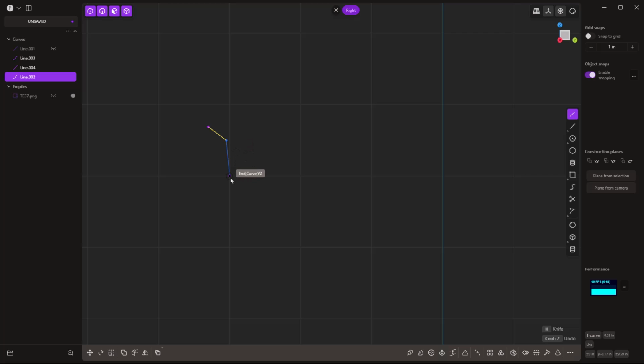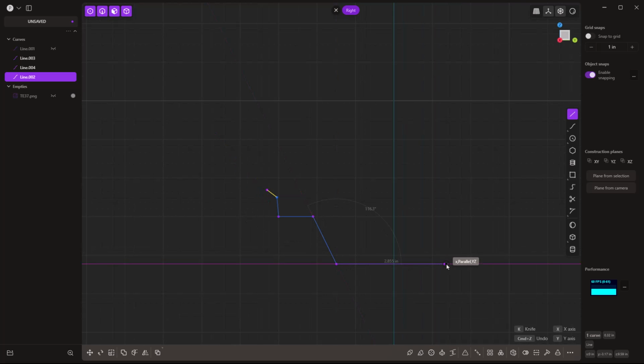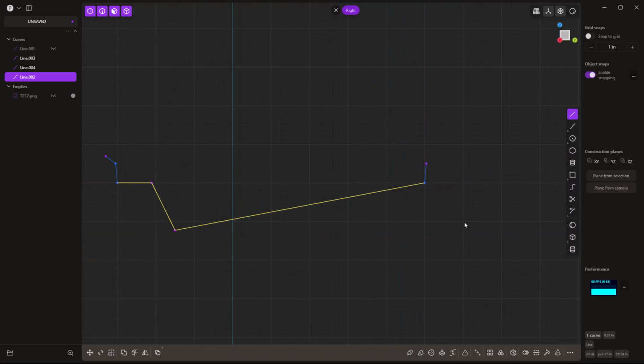So with these rims, oftentimes they'll come back a certain amount, and that's going to be sort of that front dish. If you're doing a rear-wheel drive car versus a front wheel drive, then the front wheel drive will be much less of a dish because the mounting flange needs to account for the stub axles and all sorts of stuff that has to happen on the front of them. But the rear wheel drive cars can obviously be a bit deeper. That value right there, roughly 0.9 inches, that's going to be the dish of the rim. And then we're going to have a section that comes down, and this is going to be where our spoke actually attaches. And from here, I'm going to go ahead and pan this over. I'm just going to simply come back and connect to there.